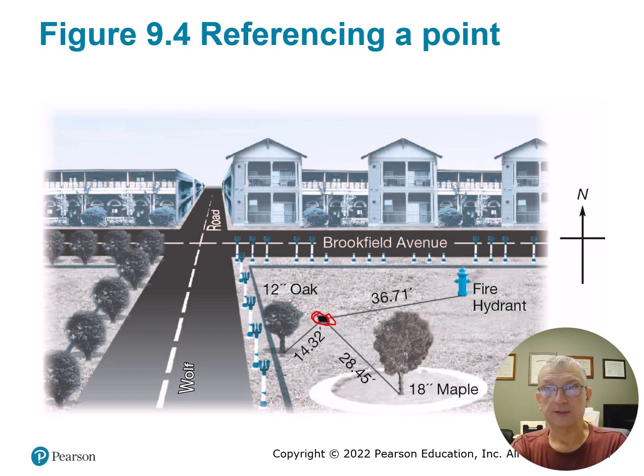In some areas, they still use hub and tacks, or just hubs in some cases, so I'm told. And a hub and a tack is a wooden peg that's usually driven down into the ground flush, and then a stake tack, which is only about 1 inch long, very sharp, is mashed down into this stake to make a precise point to set the instrument up over.